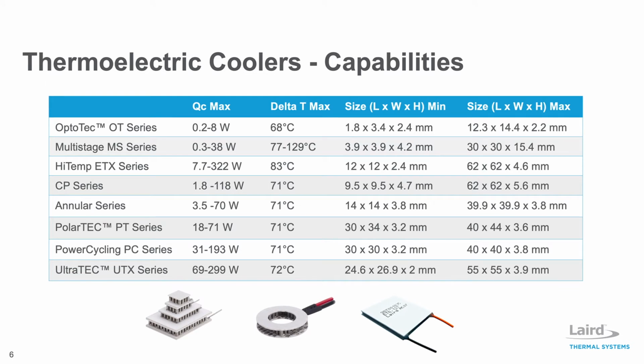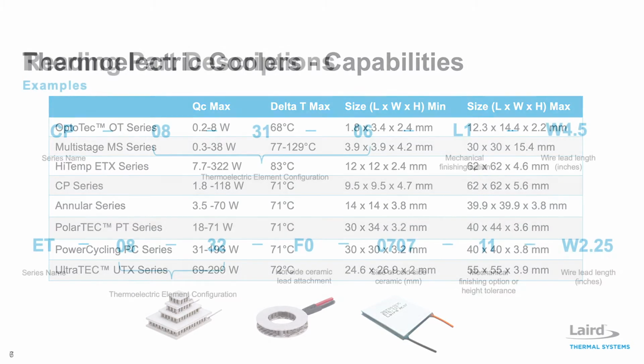Thermoelectric coolers can heat and cool by simply reversing the polarity, which changes the direction of the heat transfer. This allows temperature control to be very precise, where up to 0.01 degrees C can be maintained under steady-state conditions. A standard single-stage thermoelectric cooler can achieve temperature differentials of up to 70 degrees C. Thermoelectric coolers can cool devices down to well below ambient. Colder temperatures can be achieved down to minus 100 degrees C by using a multi-stage thermoelectric cooler in a vacuum environment.